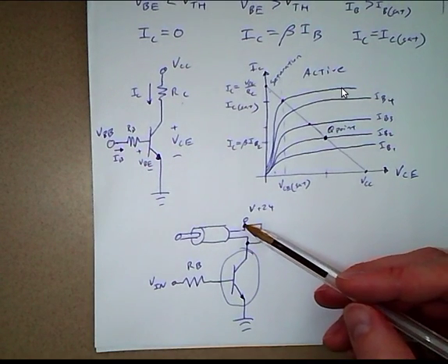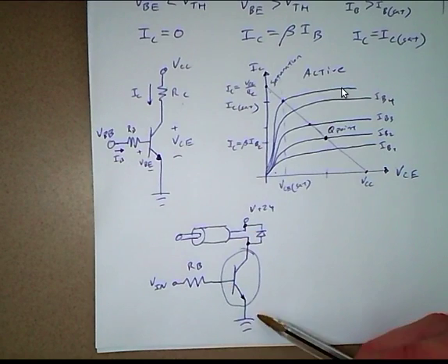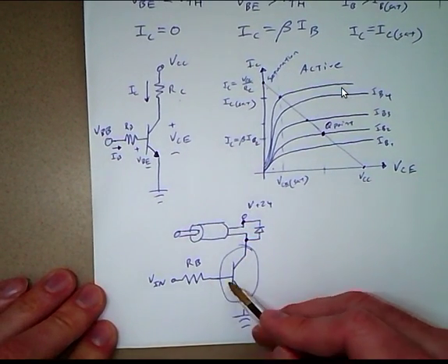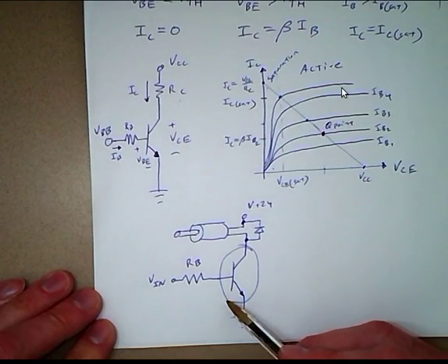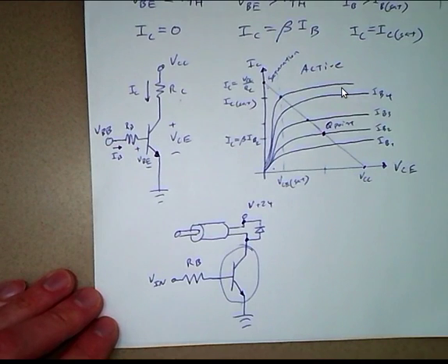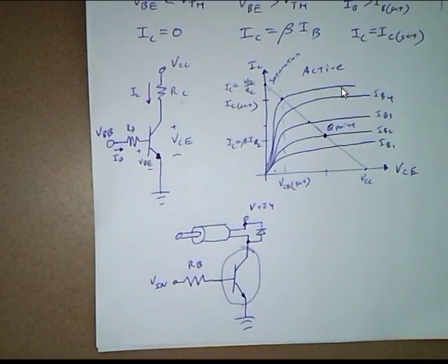The current going through the solenoid is going to be a function of the current going through the base. So this is the collector current, and this would be the base current. And the base current just depends on our value for Vin, either 5 volts or 3.3 volts, and then the resistor value, RB. So knowing the gain for the transistor, we can determine what value for RB we need in order to use this as a switch.